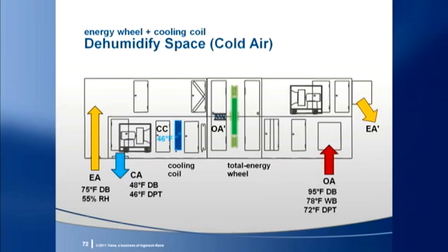What cooling sources could work for this application depend on how densely populated the space is and the space latent loads. For a chilled water system, the closest reasonable approach between the leaving air temperature and entering chilled water is 4 degrees. So here we would need 42-degree chilled water or colder. Most packaged DX equipment is not designed for this low of a dew point, so that option may be limited, especially considering the capacity required for this example is 175 CFM per ton.